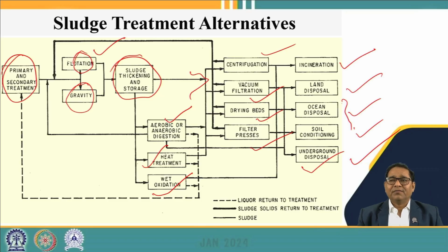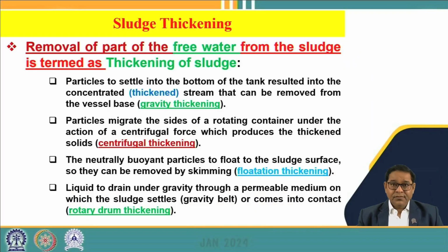So like we can make an open pit and then we can dispose this into the pit, cover with the soil. So this can be used for disposal of dewatered sludge. This slide says like different types of systems, different techniques which are adopted for the treatment, dewatering and drying, and then finally disposal of the sludge.